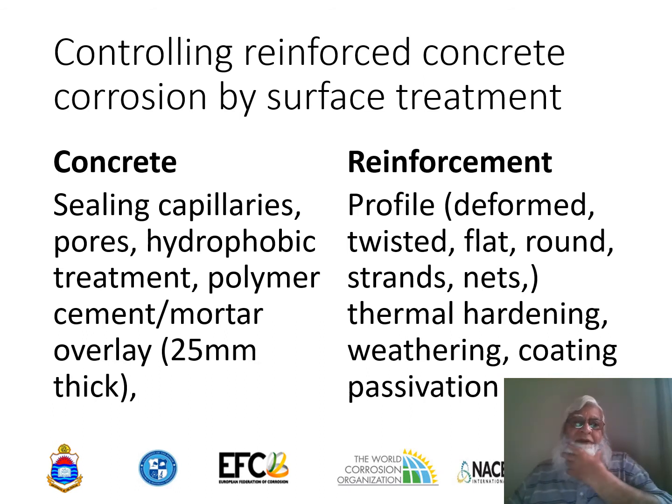We can also use hydrophobic types of coatings or treatment, which can also prevent or repel the water from entering the concrete. Other is polymers that can be applied to the surface of the concrete and the cement mortar, or put in as an overlay, and the overlay must be at least 25 millimeter thick to act as a moisture preventer.